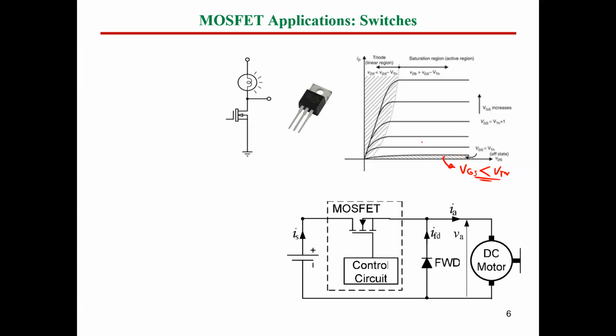The other mode of operation we discussed is the non-saturation mode. For the non-saturation mode, as you can see, with a very small increase of VD and increasing VGS, the current ID is going to increase. So mainly we use VGS to control. Increasing VG is going to increase our current because the curve will change, and the current will increase, as you can see here.